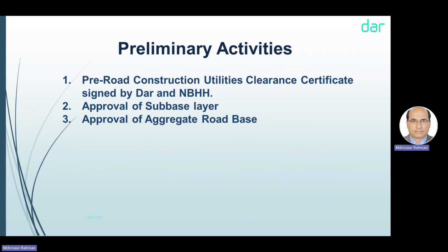Later on, in many projects we saw that after starting the road sub-base, we found that this duct is missing. To avoid this, to ensure the quality of the works and avoid any rework, we have to ensure that this clearance certificate is obtained. It should be attached with the WR. Without this form, we should not approve this WR. It's very clear.